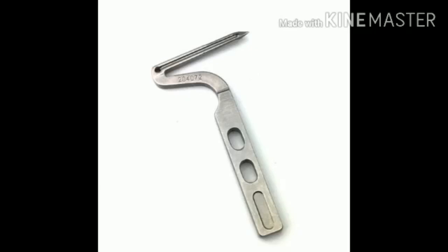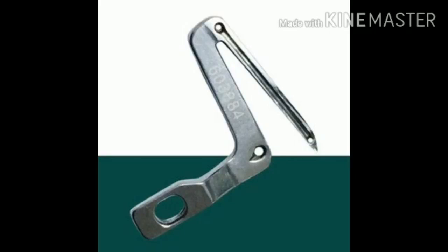As you can see, this is our looper. When a needle is bent and repeatedly hits the looper, it may break or bend it. Also, incorrect winding of threads onto the bobbin damages the looper. Excessive tension to the bobbin threads and incorrect fitting of the bobbin case also damage the looper. Or maybe upper tension is too tight, or thread may be wrapped around the spool holder or thread guides or caught on the spool thread slot.